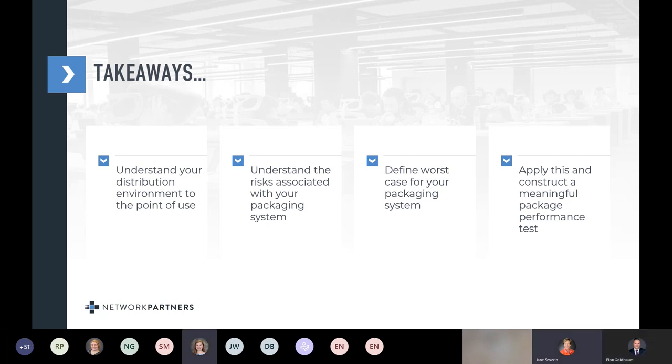All right, thank you. Is it true that you need to perform all of seal strength, seal integrity, whole package strength, and whole package integrity? To conduct all of them, not necessarily. It's good practice to conduct at least two in addition to visual. But all of them, not necessarily, but at least two. Bubble immersion or dye testing.